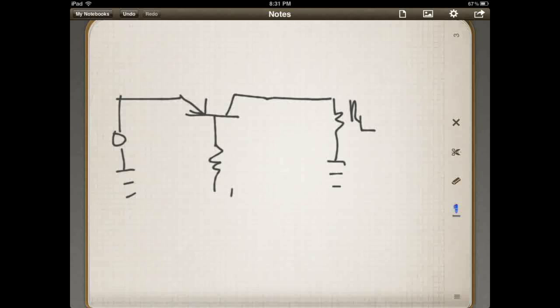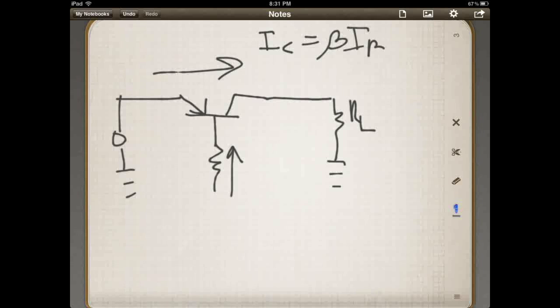Now the only thing you have to watch with it is the power dissipation. That's where you have to watch what kind of voltage you've got out here, as well as what kind of current you're pushing through, because remember V times I is P, your power. So back to the data sheet, that's when you have to worry. Let's go back up here. Oh, it's right here.